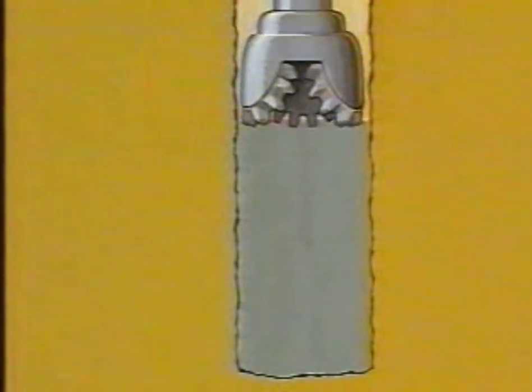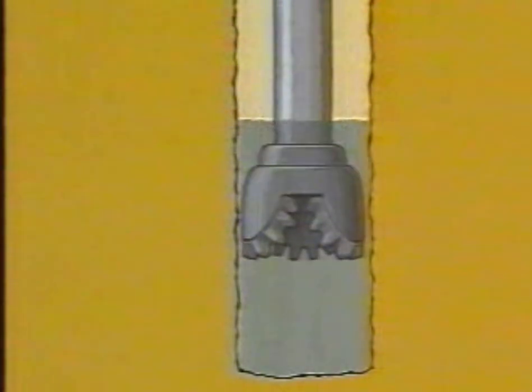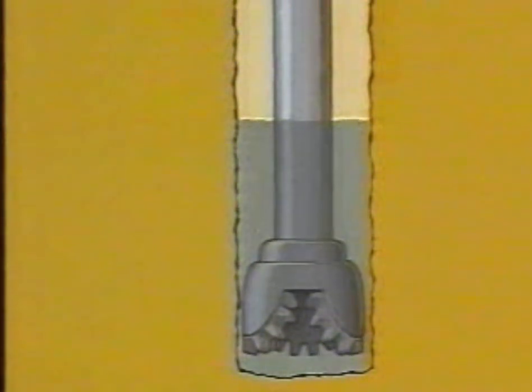When drilling out or dressing off a cement plug, or when cleaning out after cementing a liner, it's possible that green cement may lie undetected in the hole. When running in, the drill string can become planted in the cement. If the cement flash sets under pressure, then it's quite possible for the drill to become stuck.